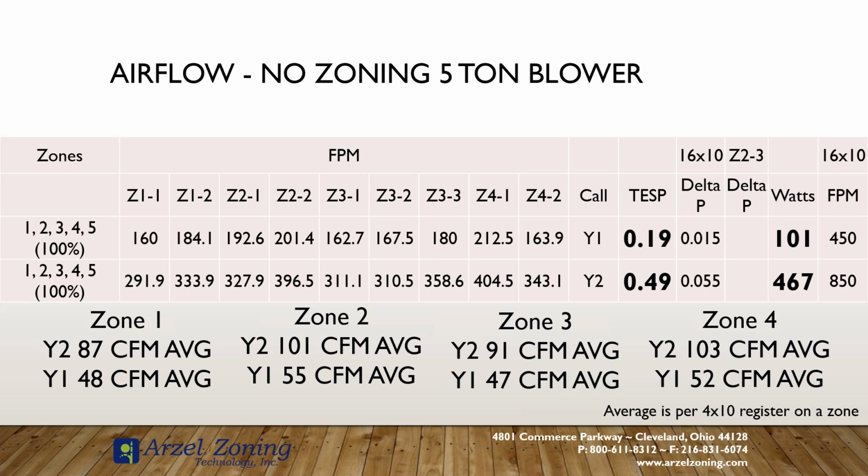So I'm not delivering a whole lot of airflow. Great for circulation if I'm trying to clean the air in my home, but not necessarily for BTU delivery. It's great for air conditioning because that lower blower speed is going to allow for a much longer run cycle. In these northeastern states, I'm in Northeast Ohio, it allows us to dehumidify the air more effectively, and that's going to improve the comfort a lot greater than having large BTU delivery.